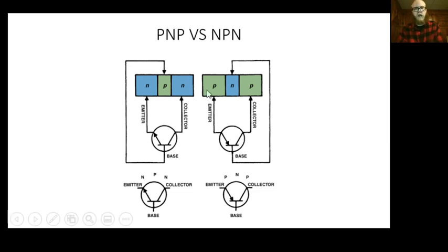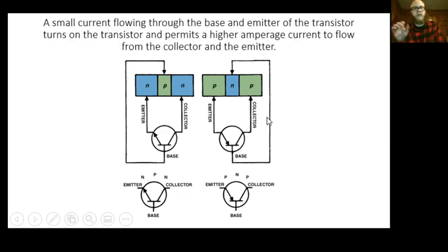deal. On a PNP style transistor, well then current's going to need to flow this way. So here I was putting voltage here, flowing current towards my ground. Well, in this case, PN, remember positive side of the circuit, negative side of the circuit. Voltage is coming in here all the time, and to allow it to flow from the emitter to the collector, in this case, it's just backwards from our NPN style. Then I need to supply ground at the base, which would allow this little bit of current to start to flow, and then the larger amount of current to flow after the fact. So that arrow is going to really help us identify in schematics what type of diode or transistor we're working with.